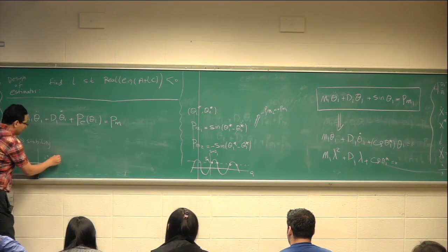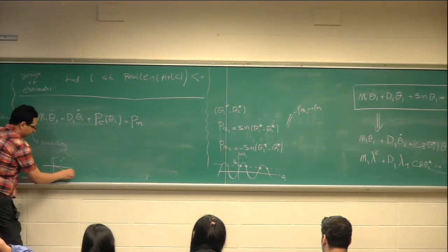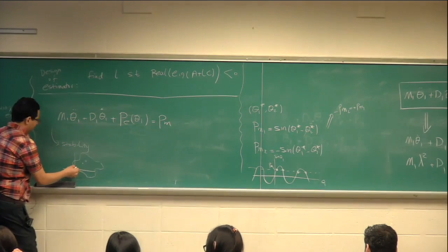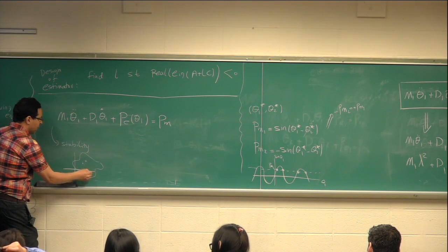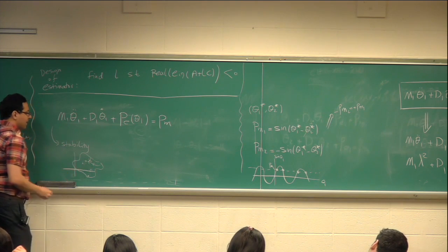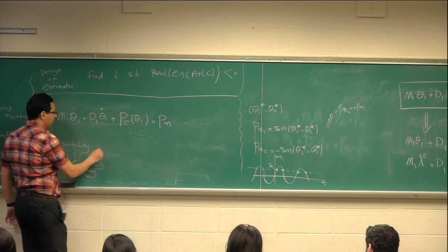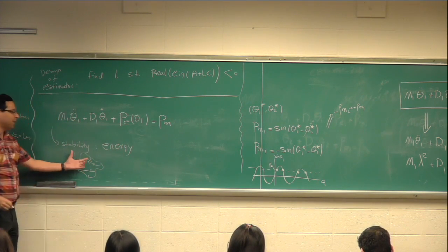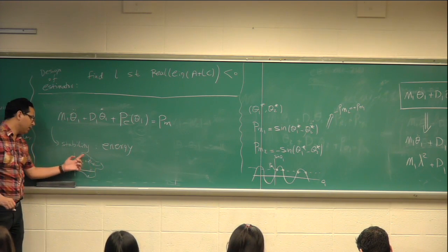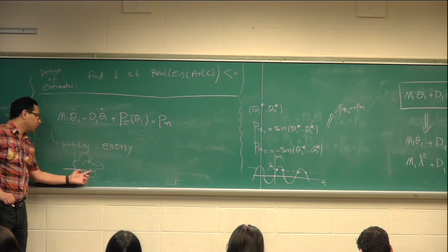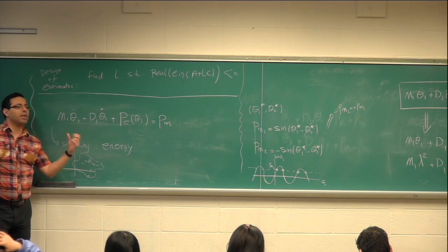If I'm looking for a region of attraction, what is the region over which, if I perturb this to any point inside the region, I eventually come back there? We said if we care about that, we have to do Lyapunov, or an energy function. We calculate the energy of the system and then say there is a region over which the energy reduces. If I start from here, the energy reduces, goes towards 0, that's an equilibrium.